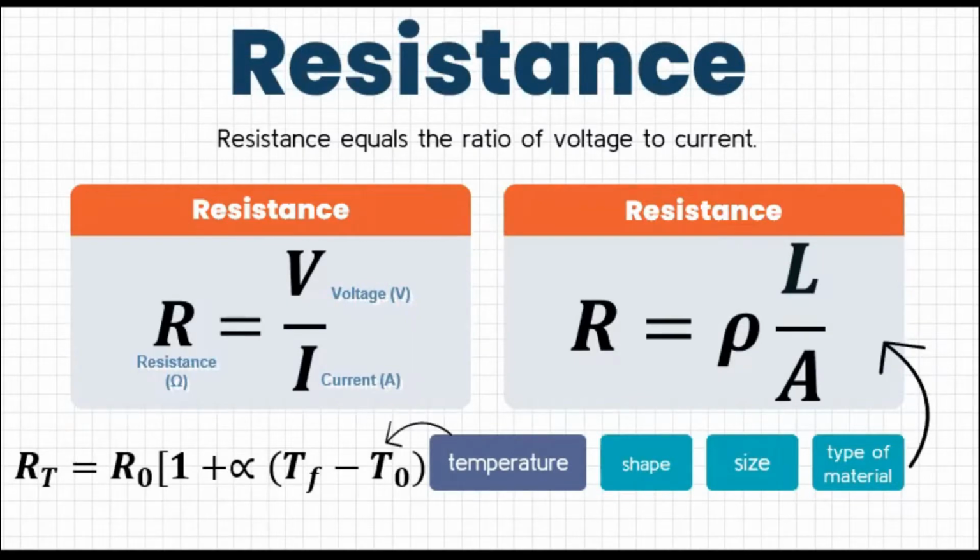So directly proportional po, take note, in metals, ang resistance and temperature. Pag increase ng temperature, pag increase din po ng resistance. So how does that happen? If nag-i-increase yung temperature natin, mas umiinit yung panahon, the charges or the atoms inside a metal become excited. Once na-excite po sila, nakaramdam sila ng heat, so nag-i-increase din yung speed nila. And once na nag-increase yung speed nila, the vibrations between the moving charges affect the value of the resistance. Kasi nami-measure po natin ang resistance by the vibrations produced by our charges.